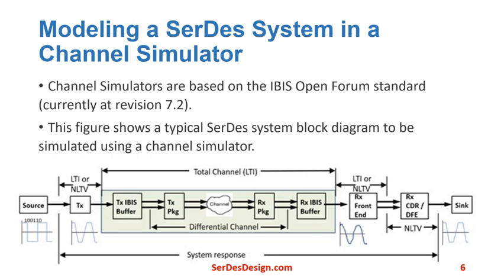Each part is optional and may be represented using S-parameter files. There's the Rx IBIS-AMI model. The IBIS portion has differential input from the channel. The AMI portion typically contains an Rx continuous time linear equalizer, a clock and data recovery unit, and a decision feedback equalizer.